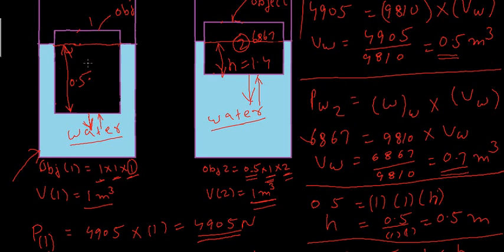That means कि बॉस अब ये 0.5 है, ठीक है. So let's say this is the center of gravity of this object which is inside the water, not the object but the object which is inside the water. So this is the point which is B. That means this is the center of gravity of the object which is inside the water, and naturally it will be 0.5 का आधा, so it's 0.25 from the base. So this is the point which is the application of the buoyant force.